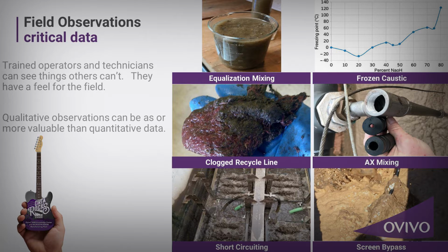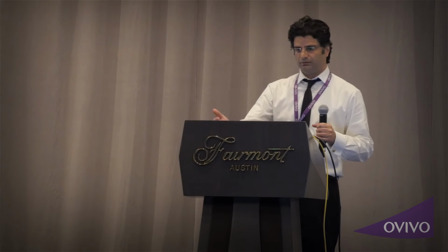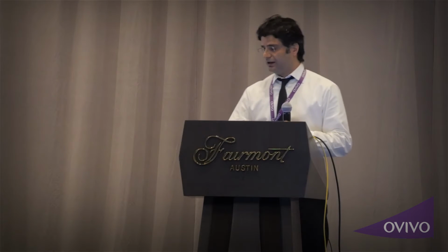Mixing is very important in an MBR system or in a biological system. We had a huge underground EQ basin without mixing, so it was covered. So we had septic condition, and every time we pumped the influent to the bar screen, we overwhelmed the system and upset the biology.